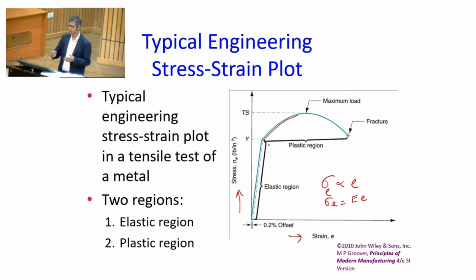And then we can have a stress strain plot, which initially has an elastic part followed by a plastic part, and the demarcation is given by the yield strength. Finally, you have a maximum load at which you have the ultimate tensile strength, and after that the load decreases and the material fractures. Load actually does not decrease. This is a reflection of necking actually, and we will not discuss much about the details of that.